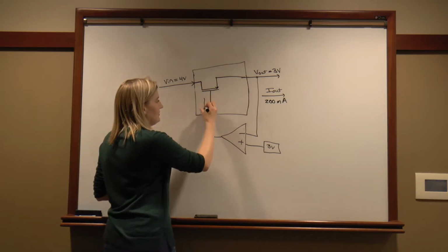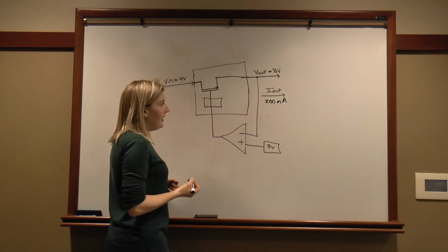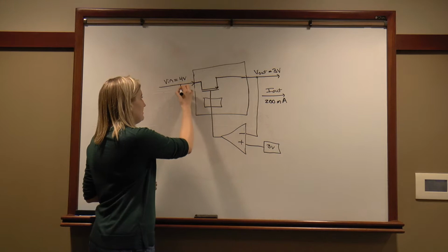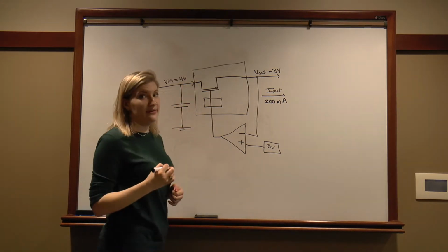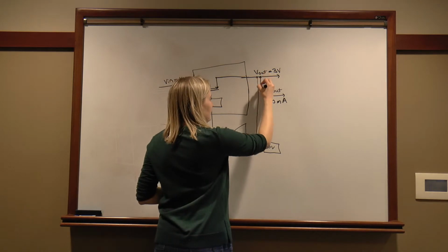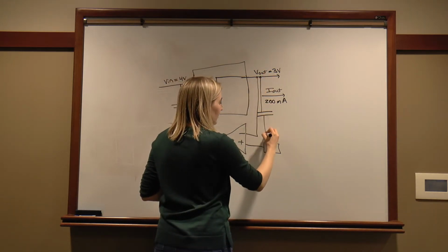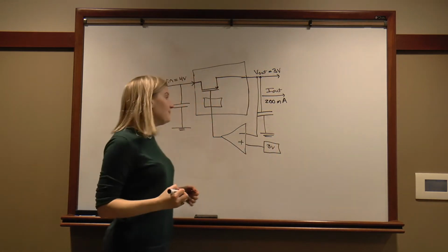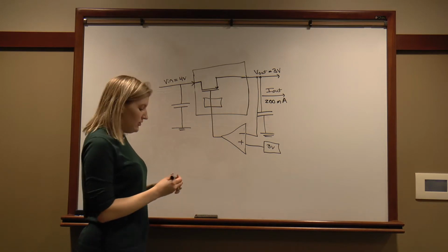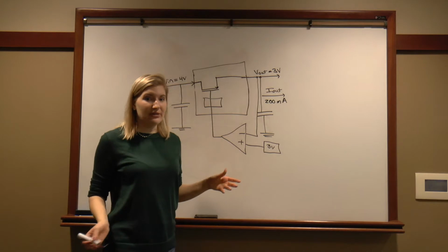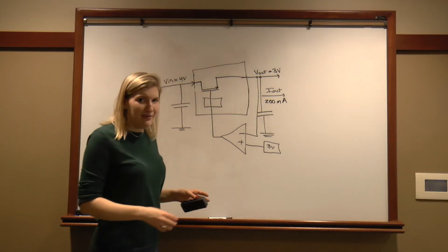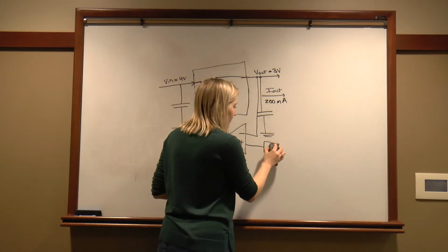We usually have some gate drive stage in here. We also usually employ some sort of input capacitance for high frequency filtering and some output capacitance here, which I'll talk about in some other videos. And normally these reference voltages here are not as high as 3 volts. We often see them around 0.6.